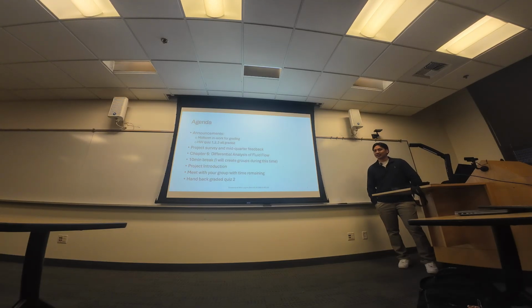Okay, and then there was not a lot of questions, but one of the problems was that hinge door swinging, and you had to find the force resultant, and there was a written portion. That written portion was just for me to know that you understand what that force resultant means. I was asking, if you calculated your force resultant and your YR, which is the distance from the start of the hinge to the gate, what would you do on the other side of the gate to prevent it from swinging?